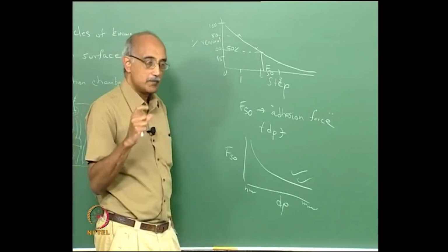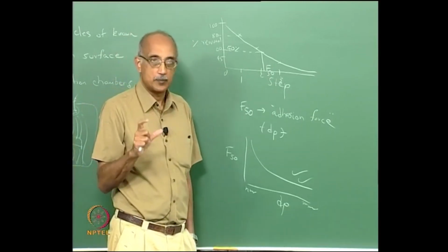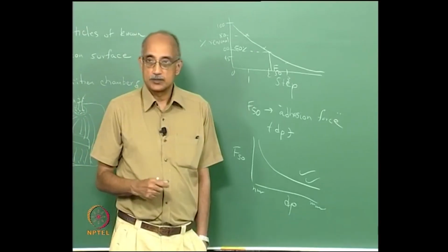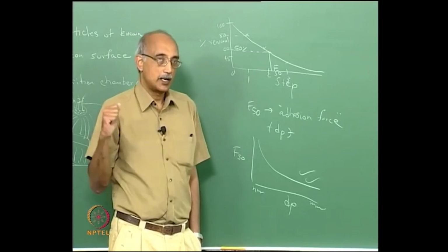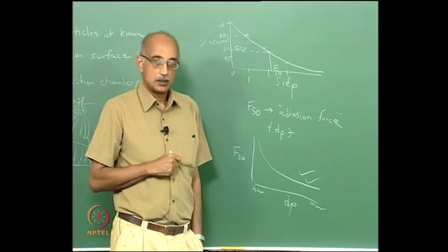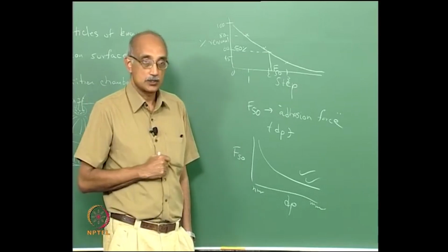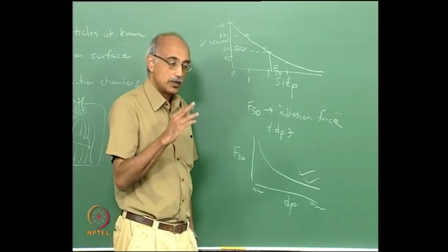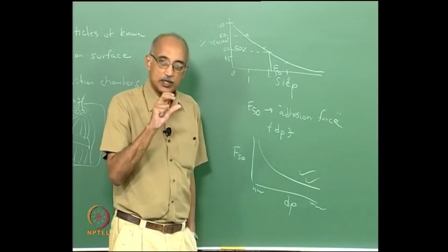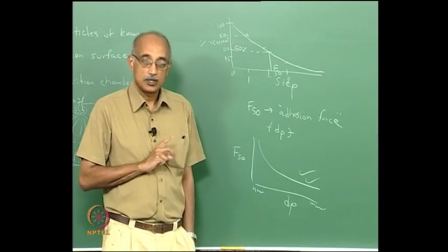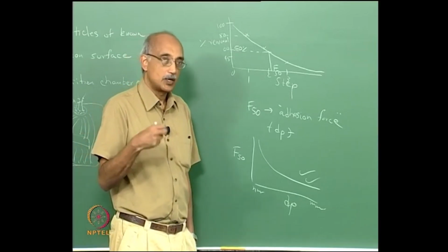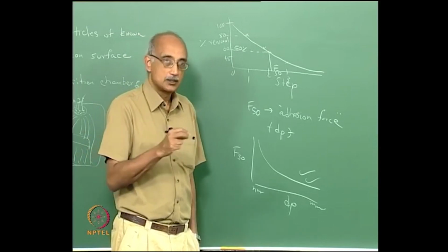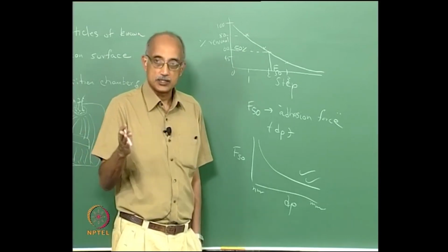For example, the same magnitude of force can be applied by scrubbing the surface with a brush, or by directing pressurized air onto the surface, or by doing sonication. You can tune these so that you get the same magnitude of force. However, what you will find is that the particle removal characteristics are very different in these cases, because they all act differently on particles of various sizes.